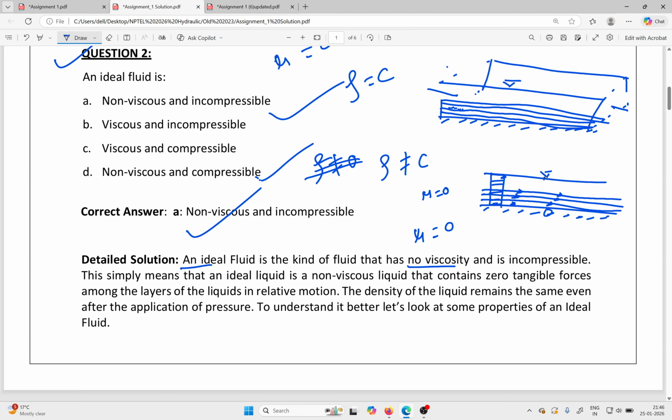So here the velocity is zero, and after that it keeps increasing. After a certain point, the effect of the wall will be negligible, and the velocity profile will be constant.